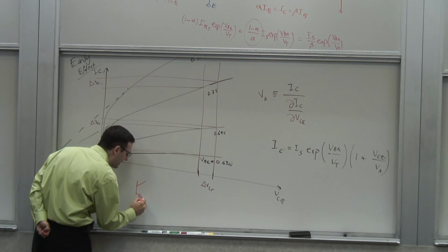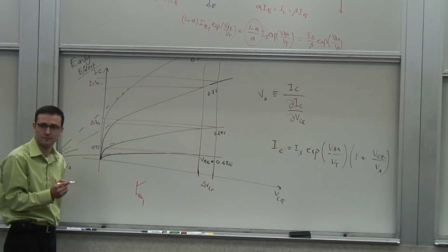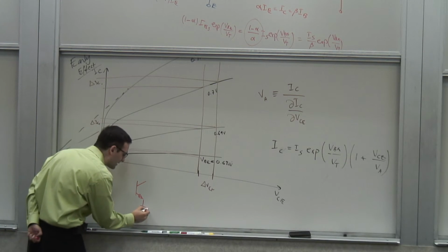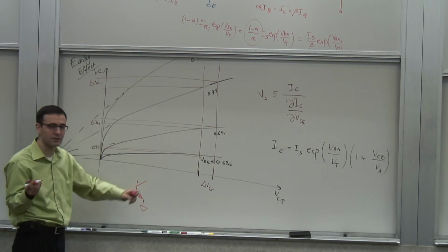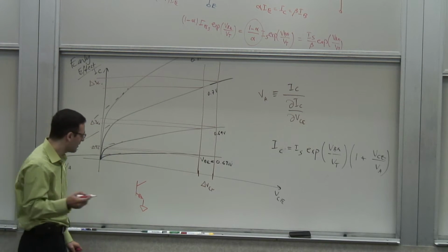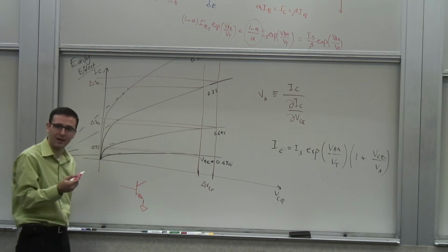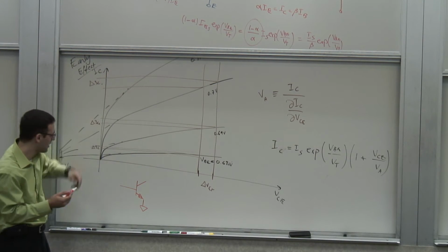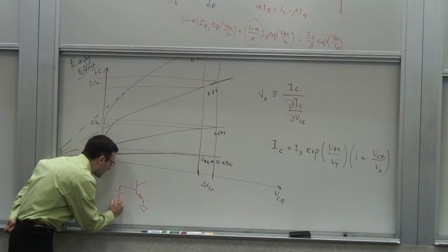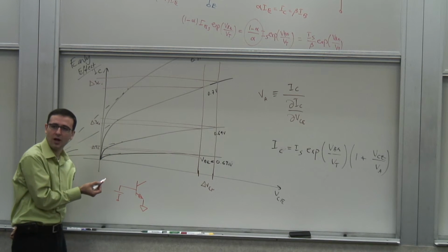It really goes back to the way we use the transistor. It's more convenient, and in fact, in most practical cases, more useful, plotting versus VCE, not VCB. The reason is that in the forward active region, where this junction is forward biased and the other one is reverse biased, this voltage is almost constant. It doesn't change a whole lot.